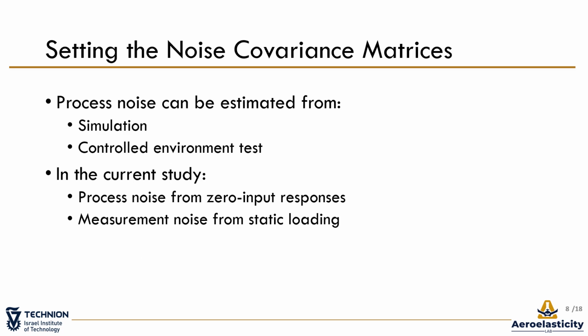The process noise can be estimated from simulation or a test in a controlled environment. In the current study, the process noise was observed from zero input responses in the wind tunnel. The measurement noise was studied from static loading. Now, let's move on to the test case and the results highlights.